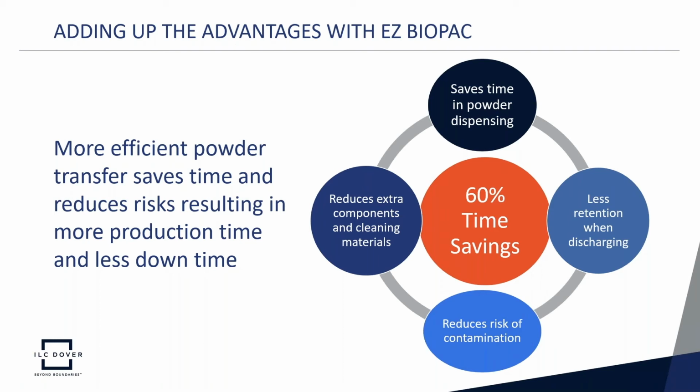The industry, the biopharm industry, is becoming more and more stringent on particulate. And the last thing we want to do is have powder bags and transfer mechanisms that actually put particulate into the environment that we have to deal with more cleaning, more validation, and so forth. So we really focus on reduced risk of contamination and reducing those extra components and reducing the cleaning materials that are needed for extra components and wipe downs and so forth. So getting rid of the gasket, getting rid of the funnel, things like that, we definitely want to eliminate.